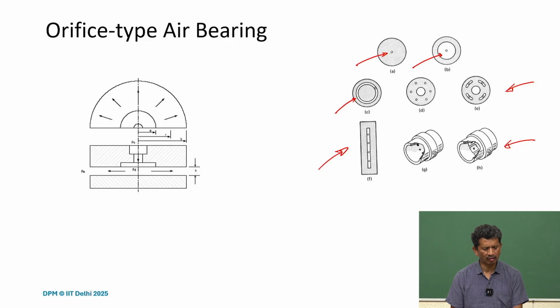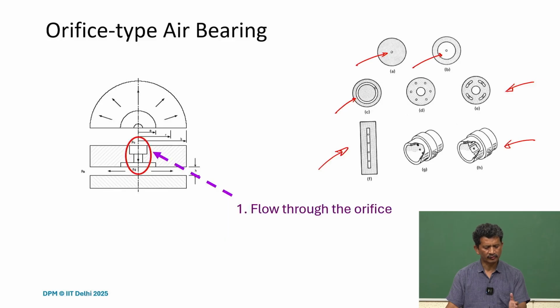All of these are aerostatic bearings. So pressurized air is fed through, and then it passes through the orifices and then passes through the bearing surface, and that's how it works. So that is the general construction structure. Just consider this circular case. So maybe consider this part with the circular pocket.